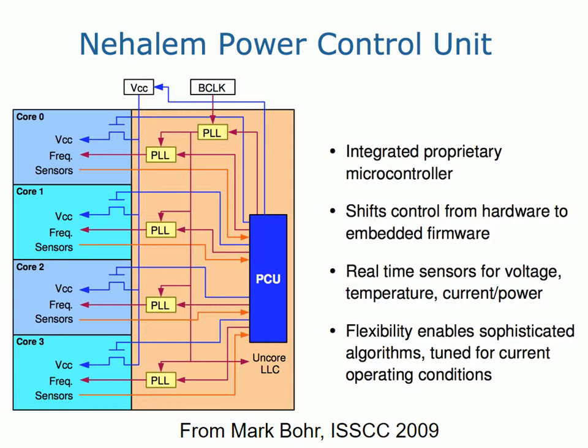different clock frequencies to the different cores, and also power gating. This is called power gating, this means that when a core is not used, it is switched off, basically. This is the best way to reduce power consumption. You basically switch off a core. This is very common in the case in which you have a multi-core processor.